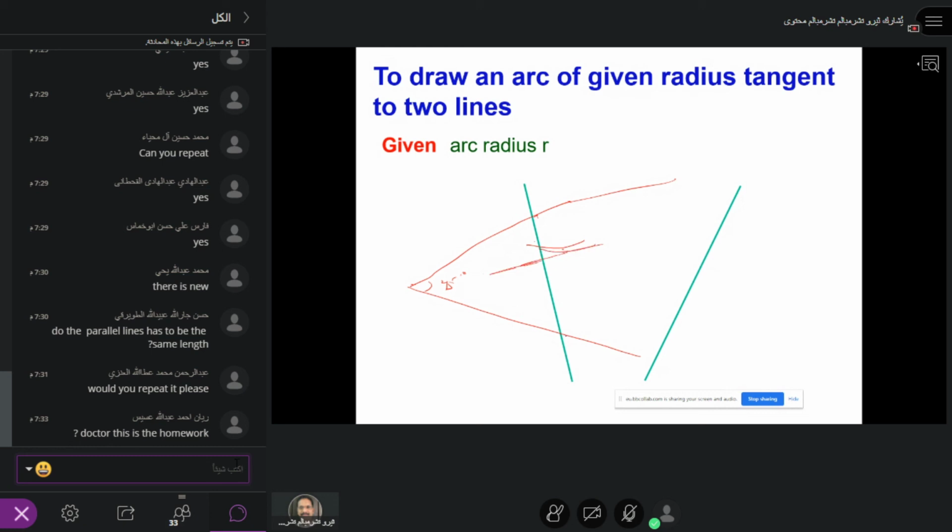Similarly, take the radius. This is R, and very similar here also. Take another one, and using your tri-square, this is the center point. And now you have to draw the tangent point by using the tri-square again as shown here, and another one here. So take this as center. This radius, you can draw the radius and then extend it as you wish for some length. That's it. But this is most important.